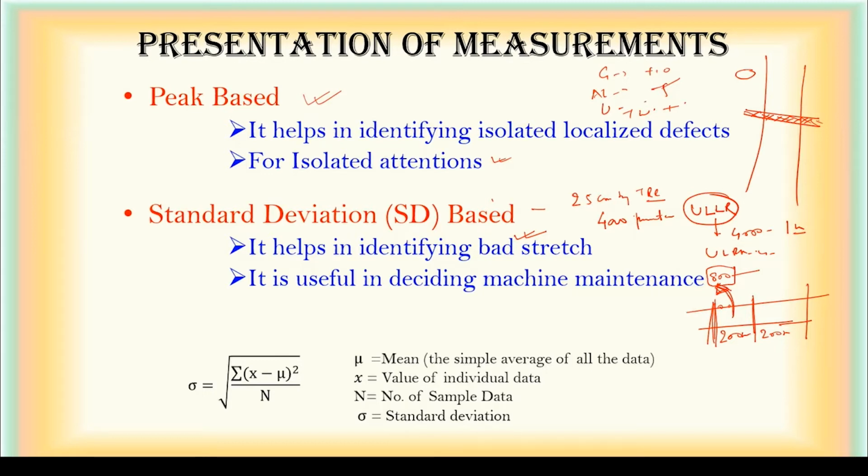अगर किलोमीटर एक से छोटा है तो लास्ट ब्लॉक will be lesser than 200 meters, और किलोमीटर अगर 1,000 मीटर से बड़ा आ गया then in that case the last block will be the 6th block. ठीक है, कई बार होता है फील्ड में due to measurement error you will find that kilometer is of 1040 meters, 1100 meters and 950 meters, इस तरह के किलोमीटर्स होते हैं. तो for this I have explained you.